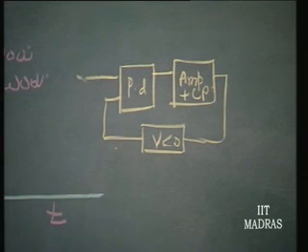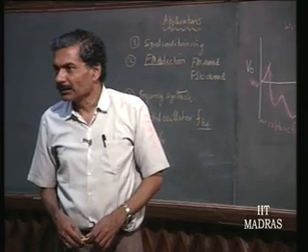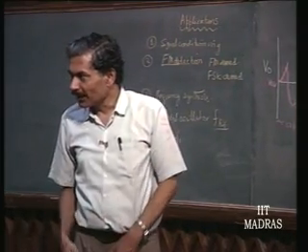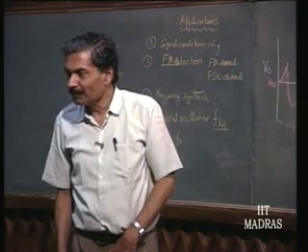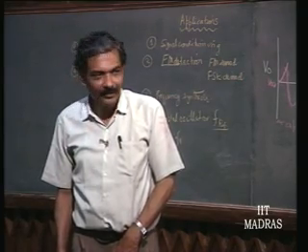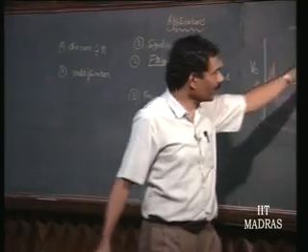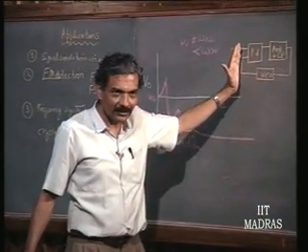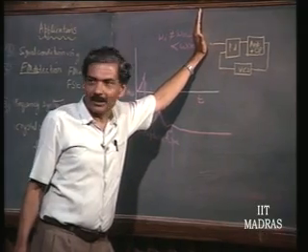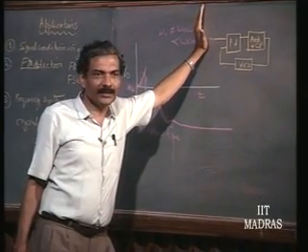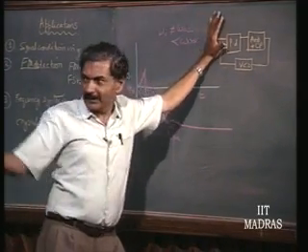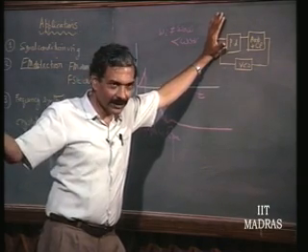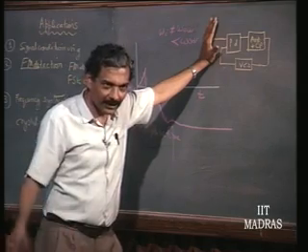That means now you are selecting the third harmonic as the output. So what is the multiplication factor? By a factor of 3. It can now vary around 1/3 megahertz, and this will vary around that. So this is called harmonic locking, but this is again not very efficient, because, as I told you, the phenomenon of capture depends upon the strength of the signal. The strength of the harmonic content keeps on decreasing.